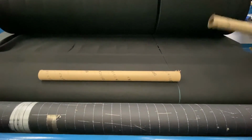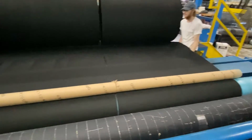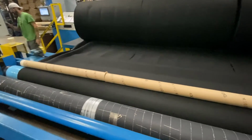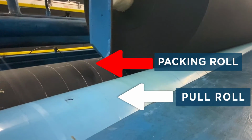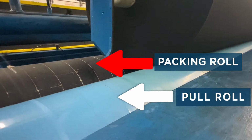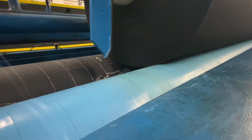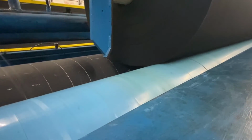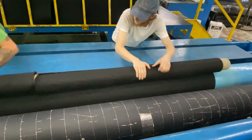Now place the core or cores on top of the tail of the material just outside the pull and packing rolls. The pull roll is running a speed faster than the line speed to help pull the fabric through the winder. The packing roll, which is known as the taper tension, is running even faster than the pull roll to provide much needed tension to compact the fiber onto the core, which will in turn provide a good tight roll build.